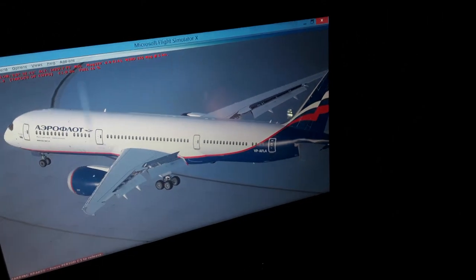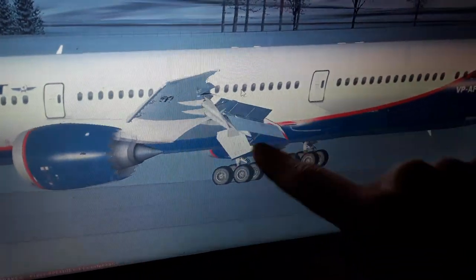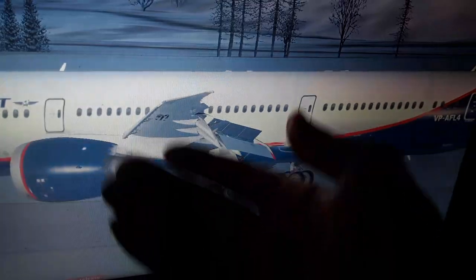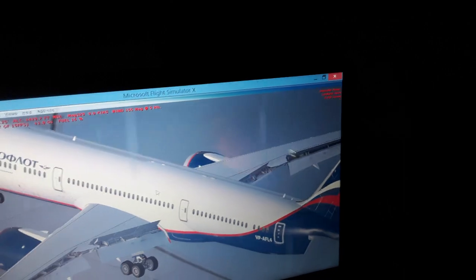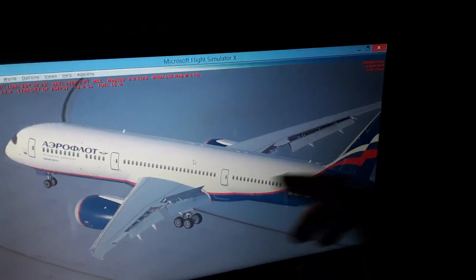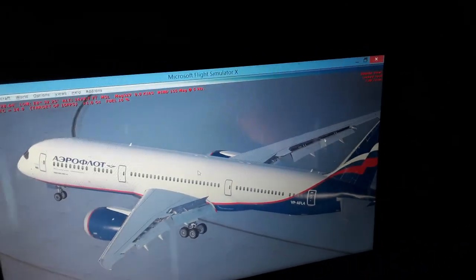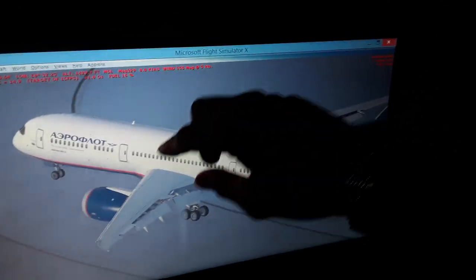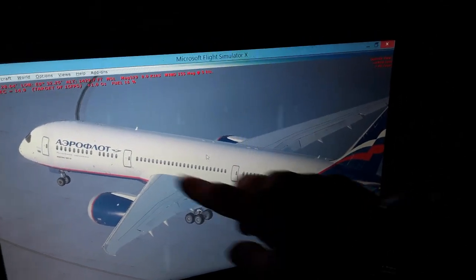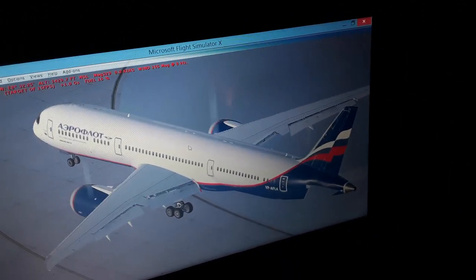So over here you can see the engines. You can see we have lower pressure below the wings. We have higher pressure when the aircraft is flying at about 300 kilometers an hour. So the air is pressurizing the weight in the wings of the aircraft up into the air. Also, as we increase airspeed, like Mach 0.9, about 900 kilometers an hour, we are going to have higher air pressure. Also, on the top surface we have lower pressure because the airspeed is moving faster above the wings, using the Bernoulli theory of fluids.